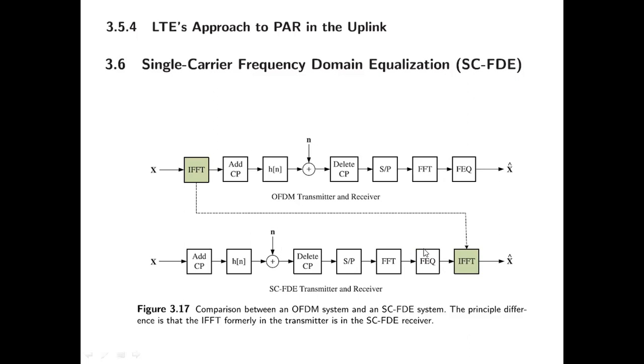And now what advantage do we have here, by the way? The advantage in this particular scheme is that while doing the SC-FDMA transmission, the signal does not have as high a PAPR as its OFDM counterpart. I hope you remember the reason for high PAPR in the case of OFDM was due to applying the IFFT.